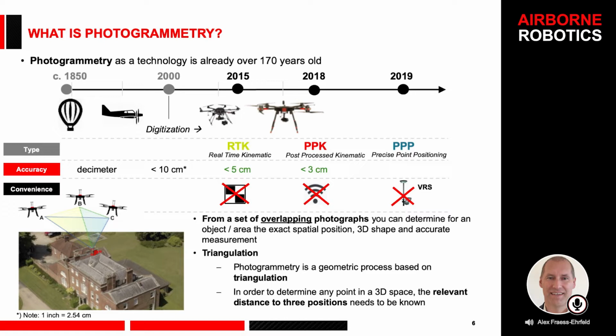And in terms of type of photogrammetry, there are 3 systems we are looking at today. So RTK, or real-time kinematic, basically in the early days, 2014-15, it was used. This was then developed to PPK. That came in at around 2018 and is the preferred choice typically today. So that's a process which is not in real time, but post-processed. And then we have a feature which is PPP, precise point positioning. It's something which has been in the market for quite a while, but it has been now developed to the standards of today's surveying, and Rob will talk about that in a minute.